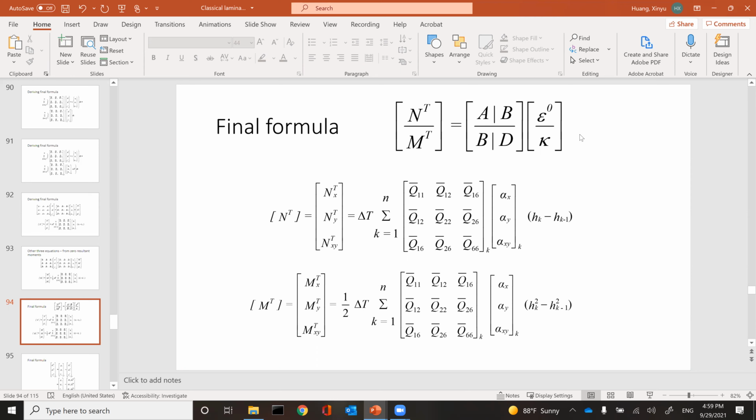One of the reasons symmetric laminates are used more frequently than others is that they warp much less. Everything is symmetric. If you're unsymmetric, it'll warp really badly. It'll be surprisingly high because the thermal expansion coefficient of polymer is really, really high. You're talking about 60, 100. So if you cure at 200 C, 300 C, 400 C, and cool down to room temperature, it'll warp like crazy. It heavily depends on layup.